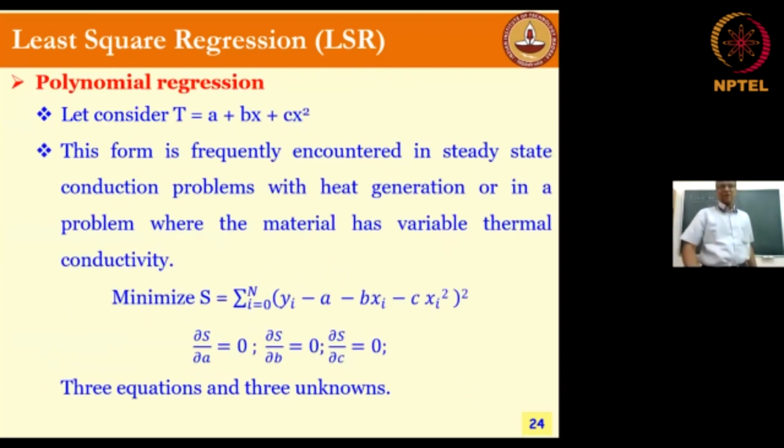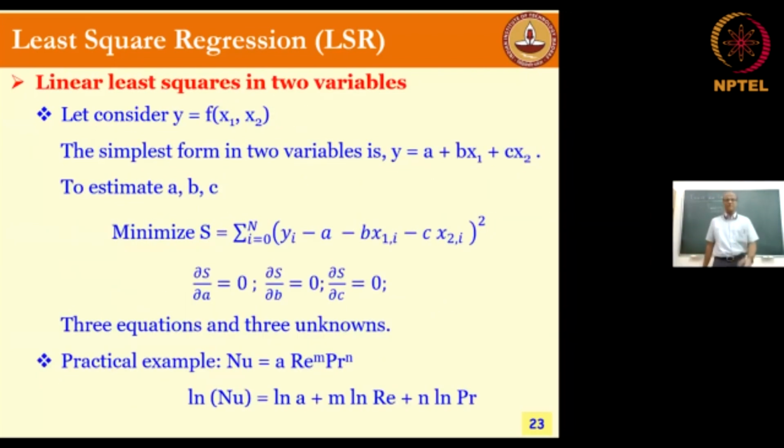Okay. All right. So you can do a lot of experiments for various values of Reynolds number and Prandtl number. Get the heat transfer rate, divide it by A delta T, get the heat transfer coefficient, convert it to Nusselt number, and then do it in Excel or you could do a regression and get a correlation. What is the idea of getting a correlation? Somebody who wants to get the result from Nusselt number doesn't have to do all the hard work. What is hard work? You did experiments, then you regressed it and gave a correlation. This correlation can be used by others so that they don't have to go through this trouble and they can easily get the Nusselt number.